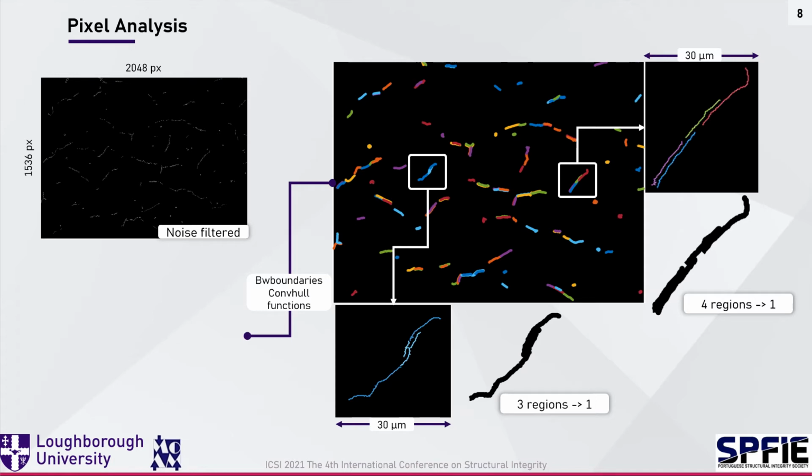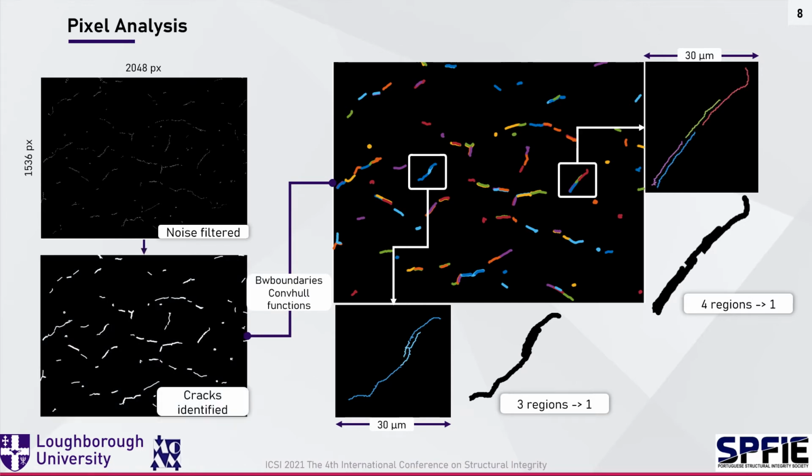The output of the function was analyzed for pixel continuity. There were instances where close regions were computed as separate cracks, as shown. In these situations, the regions were combined by appending the identified coordinates to one array. After doing this, the areas of the cracks were calculated using the convhull function. This generates a polygon around each crack and calculates that area.